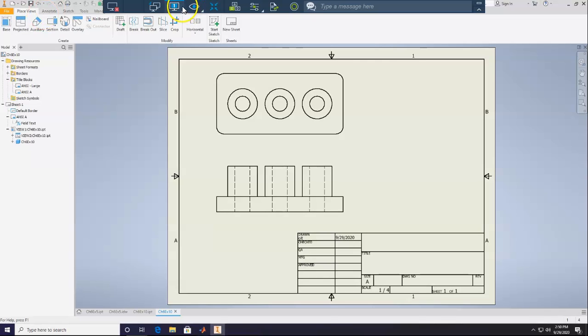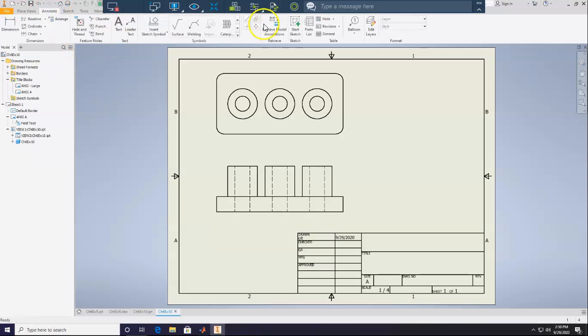Go to Annotate, add center marks, boom, boom, boom, and center lines. And because these show the edges very clearly, why did that not work? You can just click line 1 and line 2 and it'll automatically thread the needle. Okay. And let's start dimensioning.